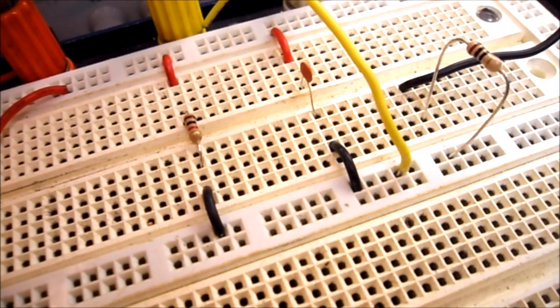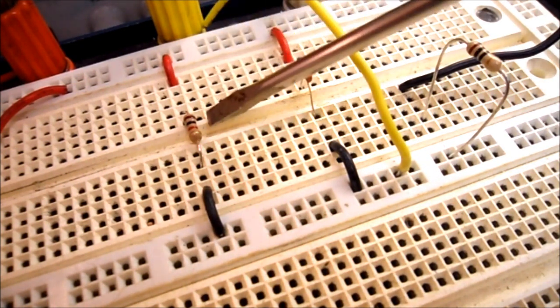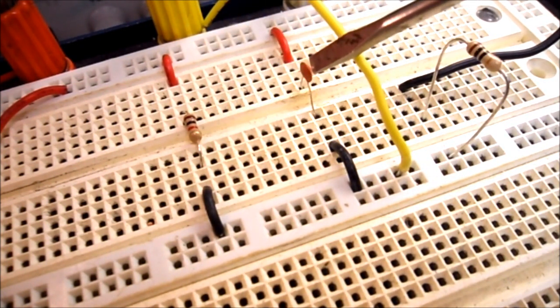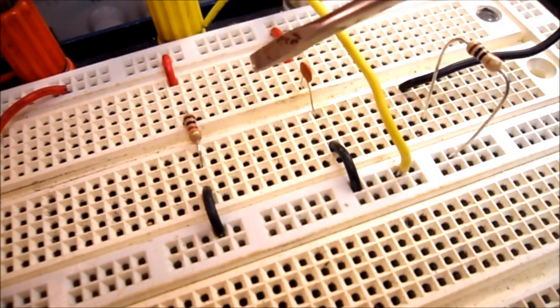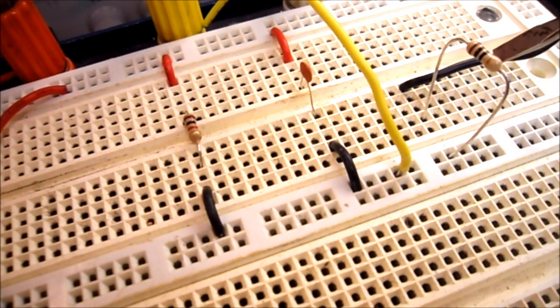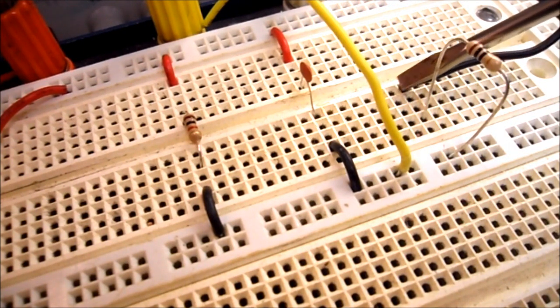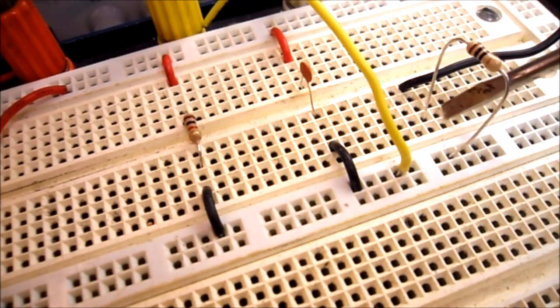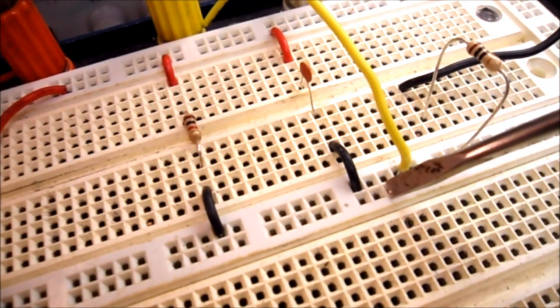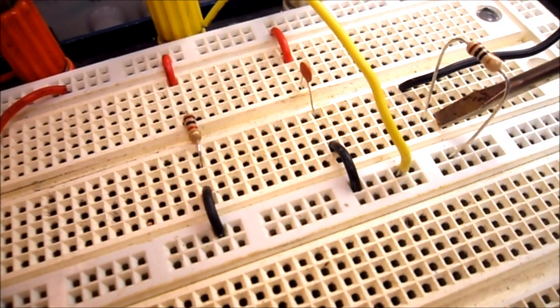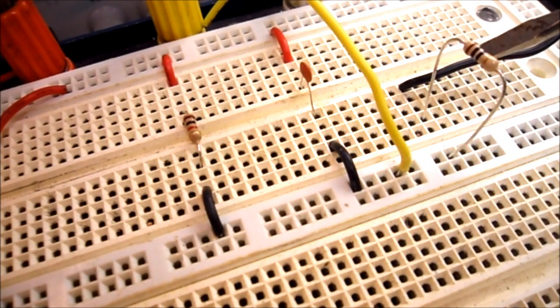So this is a real close-up of my circuit. You can see that I have my 1K ohm resistor and my 10 nanofarad capacitor, and they're in parallel. And this is my ground line, right? So the black line coming in is my main ground line. And I had a little jumper here taking ground down to the entire bus line. So now what I've done is I've pulled out that little jumper and replaced it with this 10 ohm resistor.